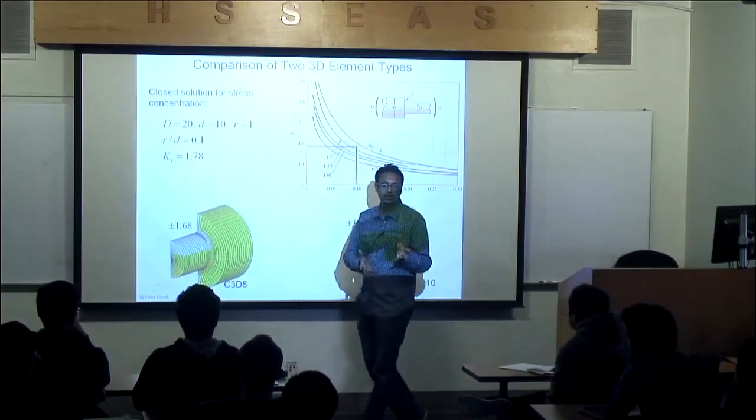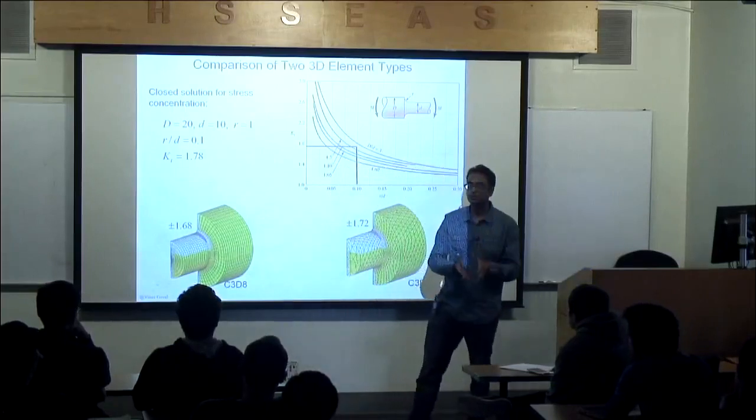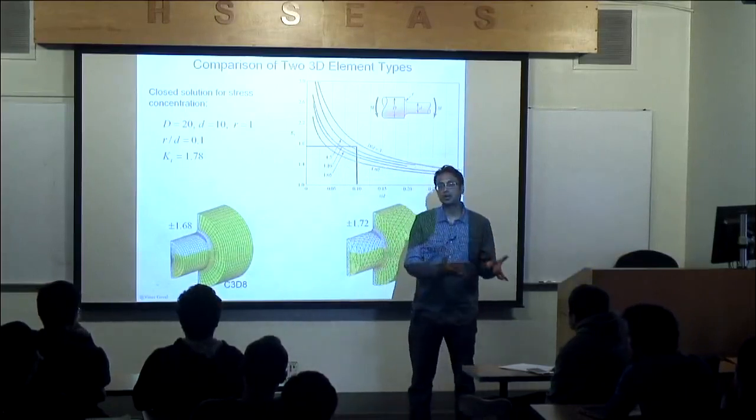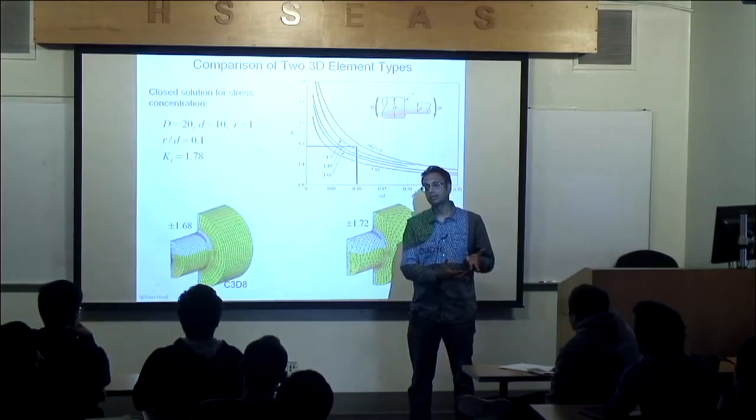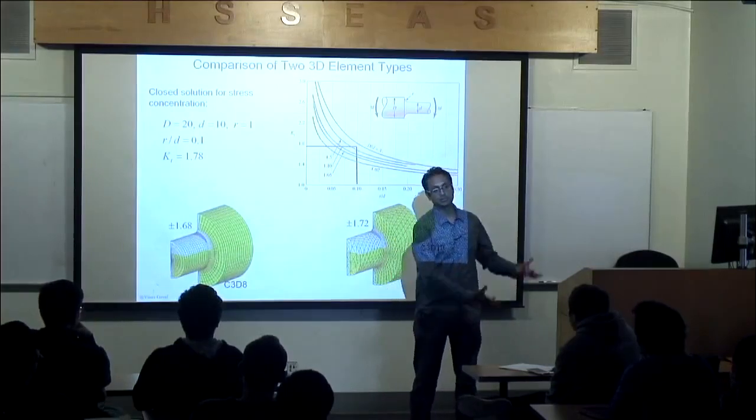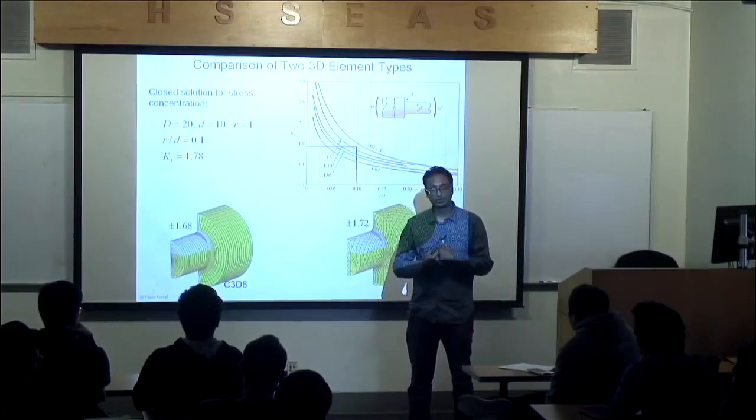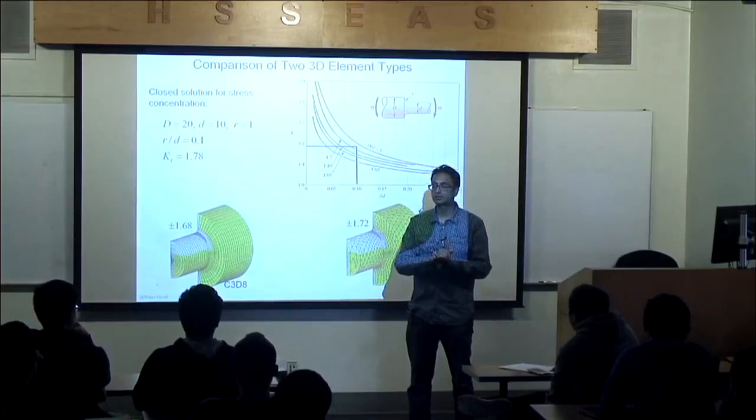They're in a theory manual. I'll open it up so you can see they're all there. So it already has all these embedded in the code, and it's basically using this information. You don't have to do the assembly. Abaqus is doing that. You apply the loads, the boundary conditions, and Abaqus solves the linear system of equations.